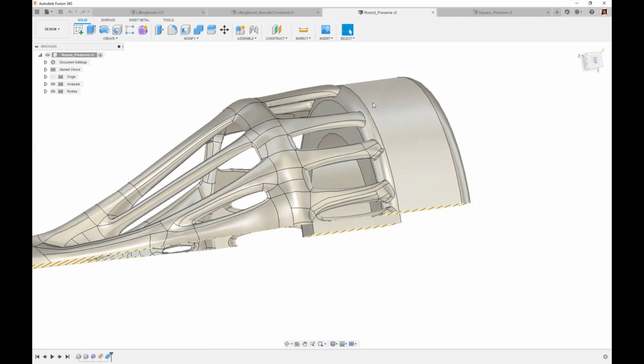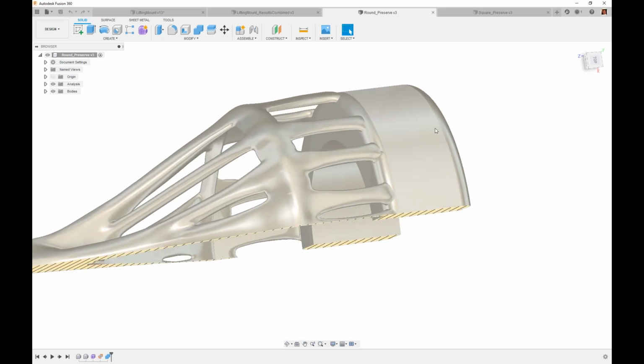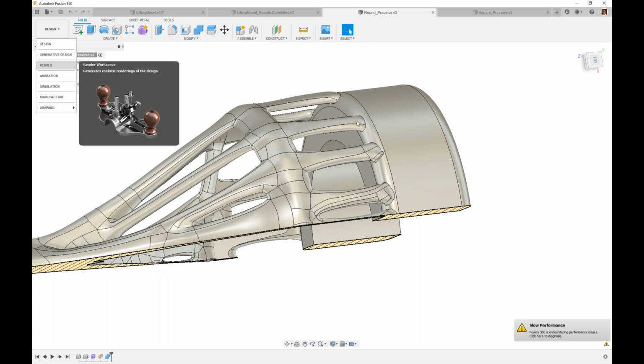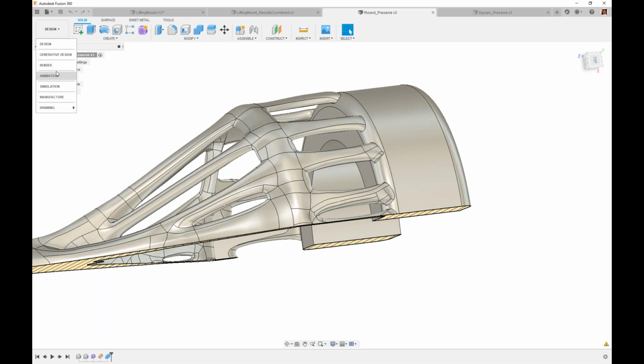The difference between those two is fairly subtle from a setup perspective. And even from a results perspective, the outcomes are very similar. But what you see is that by adding fillets to some of our geometry, we can help alleviate stress concentrations in the final outcome.